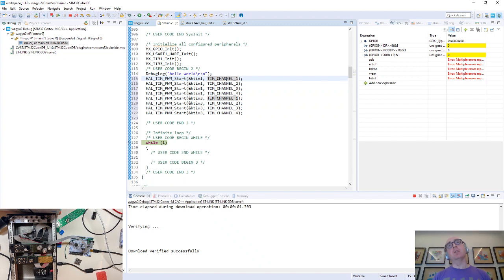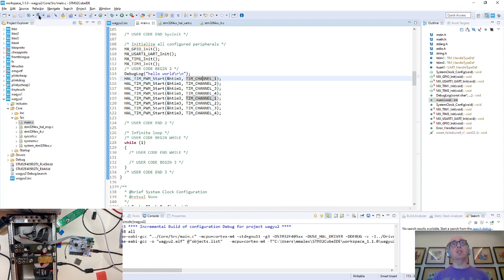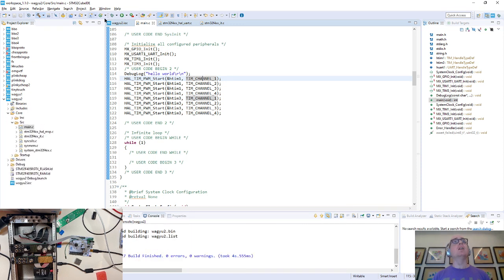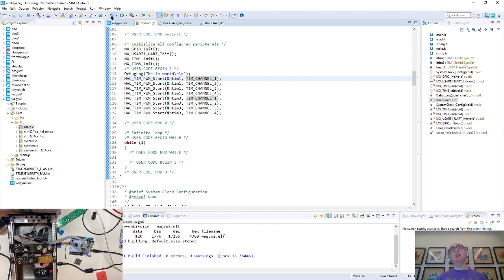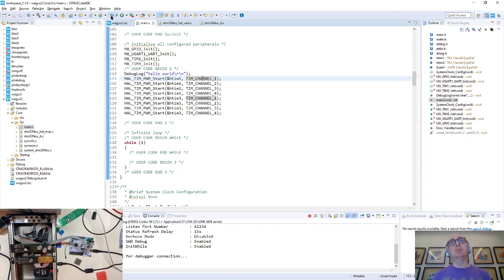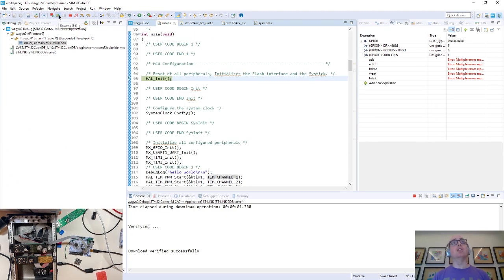It's not particularly well documented, and I was like, fuck it, life's too short. Let's try this. So, gross as it is, I just start all 4 channels across the 2 timers that we did, and we hit run. Why did I choose 1 and 3, by the way? That's because that's where the pins fell naturally when I was doing the layout. So it's kind of a back and forth between the software and the hardware and the restrictions.